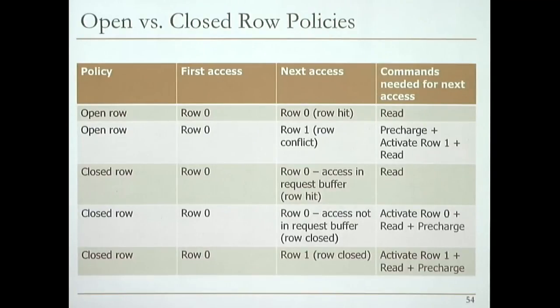And while you're activating the row, you're basically wasting a lot of time, because that activation takes a lot of time. Pre-charging the array also gives you wasted time. So a stupid policy would be closing the row after every access, without even looking at the request buffer.